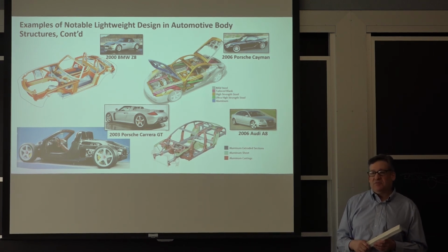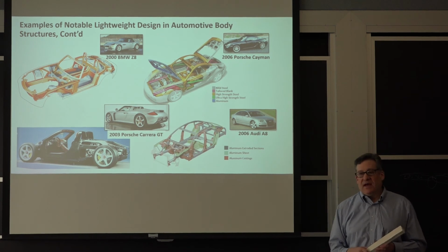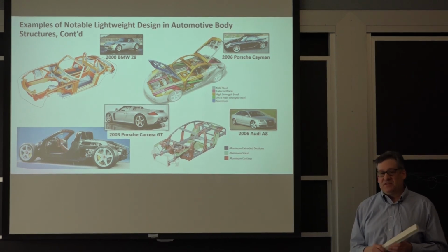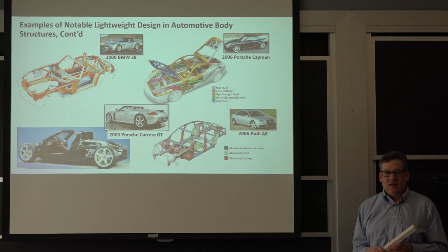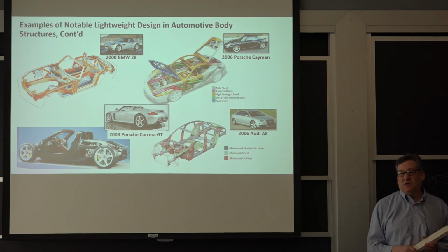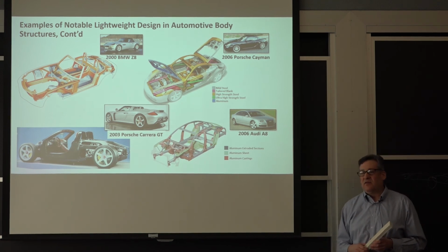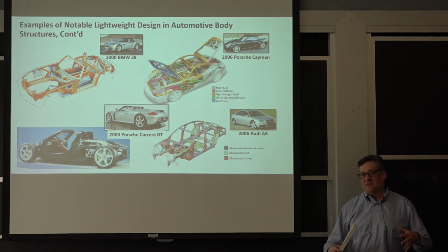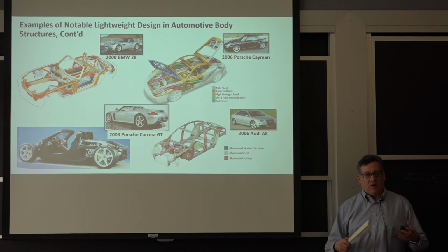So at 60,000 Newton meters per degree, you have to ask yourself, do you really need that level of stiffness? What's it really going to do for you? Having spoken to a friend of mine who was an engineer at McLaren, he said that there was no reason to have it from a safety or a performance standpoint. It was only because the drivers like the feel of the stiffer structure. It made them more confident behind the wheel, which is important. So they keep doing it.